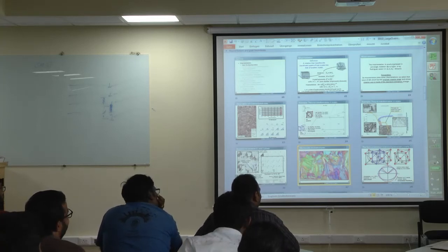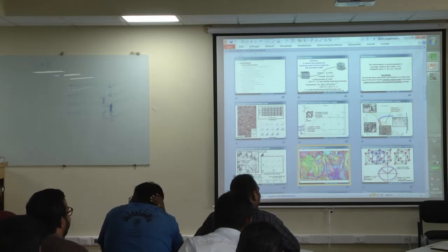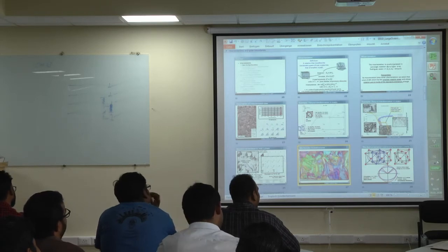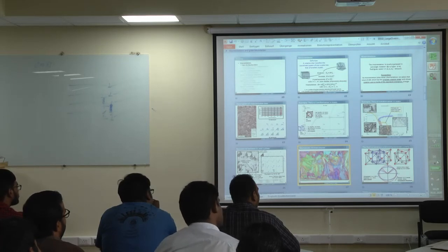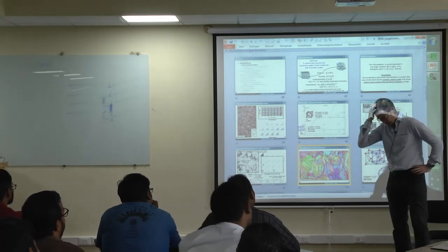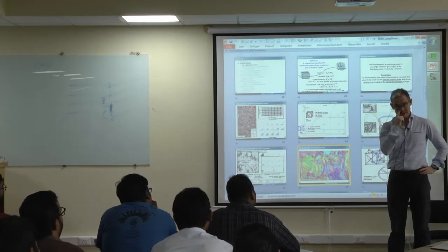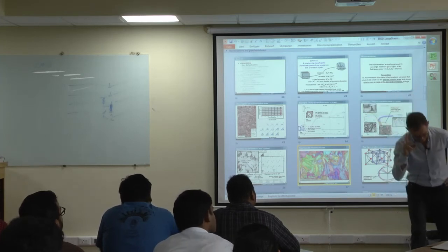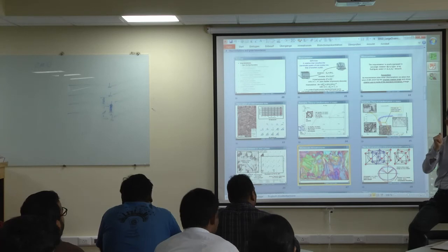No, but I'm coming to this in a moment. No, it's not a bad question, of course. It's a good question. Bad question because I don't have a good answer. So I blame the question for not having a good answer. It's really difficult to say the distinction between bainite and martensite. But I will comment on that in a little moment. The reason is, in principle, both structures are formed displacively, one at a higher temperature and one at a little bit lower temperature. And that means the process in principle is the same. It's a displacive transformation. Just the stresses are different.